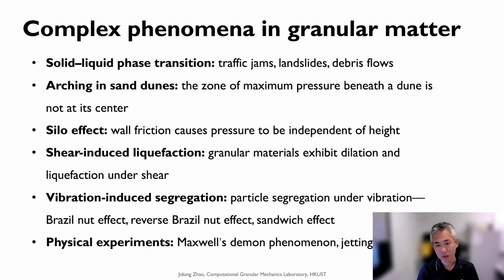If you are in earthquake active regions, a sandy soil foundation can be liquefied because the earthquake shearing force can cause what we call the loss of effective stress and strength, and then the bearing capacity of certain soils is totally lost here.